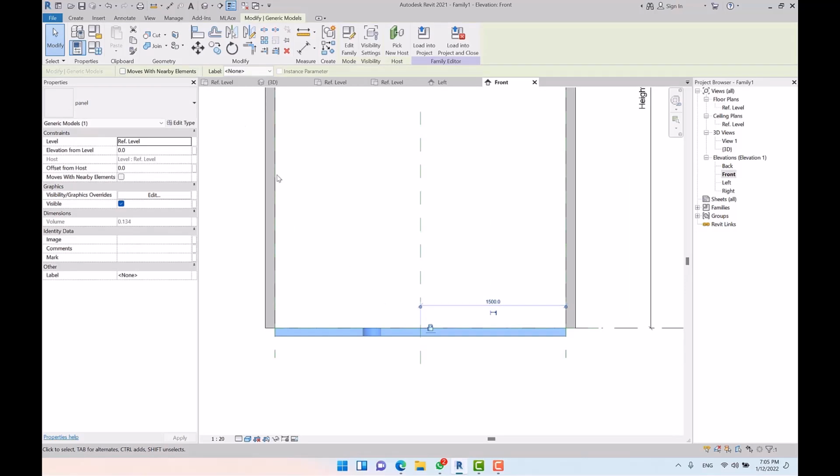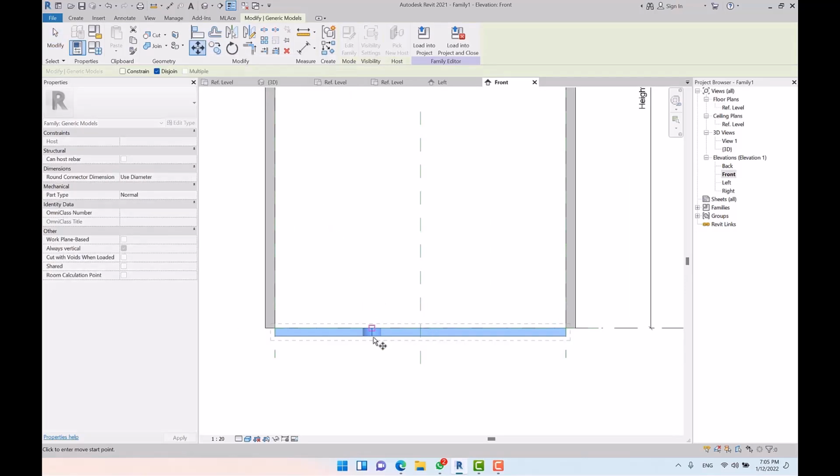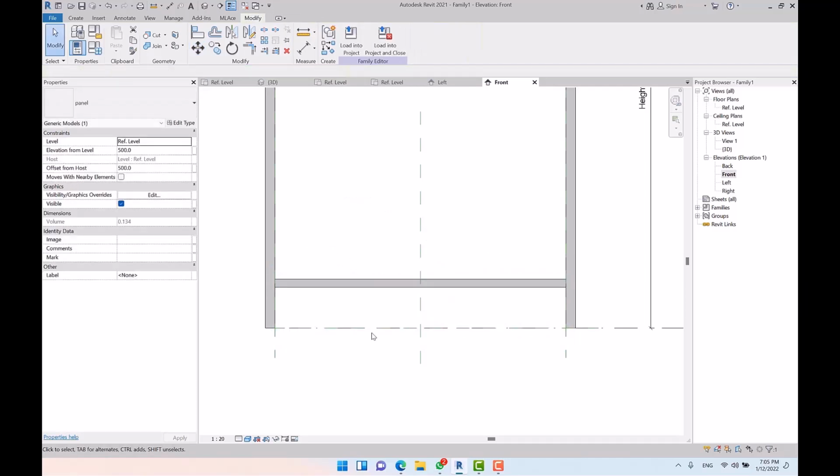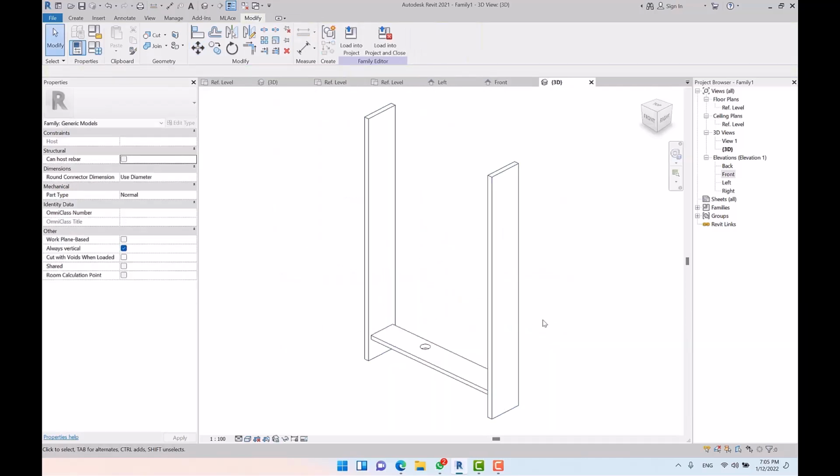Anyway, here we got the loaded panel with the hole, as you can see. I want to move it, and preferably when you are moving the panel, uncheck the option of disjoin, since it is possible to dissociate the specified families for the panel. The associated families may be disjoined, so that it may cause us problems because it removes the constraints and also the locks. I place it right here in this way.